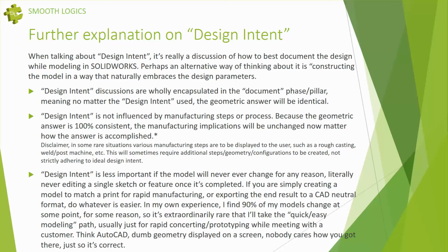And design intent is also not very important if the model never changes. So if you're literally given something and told, draw it, we're going to export this as a 3D solid and send it to China, then just hack out that model as fast as possible and send it off. If it's never guaranteed to change, you can be super sloppy. And I really only ever do that if I'm prototyping. I have a customer sitting over my shoulder, and it's easier to just draw another sketch, extrude a blob out, as opposed to go through my tree, figure out what to edit, and add that blob in an earlier sketch like would be proper. So I do very, very sloppy models, but it's almost always rapid prototyping, somebody standing over my shoulder, we're trying to prove something out, and then I 100% throw those away and build them up appropriately from the ground.